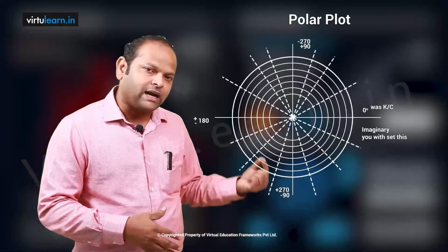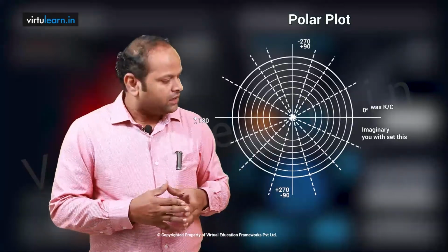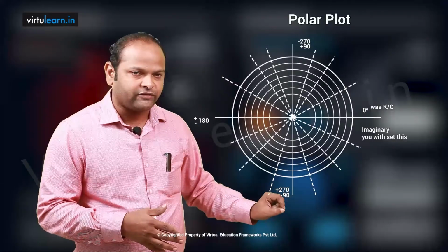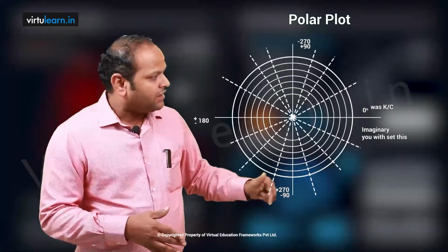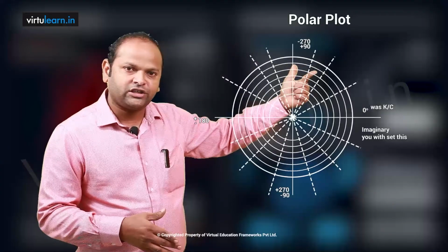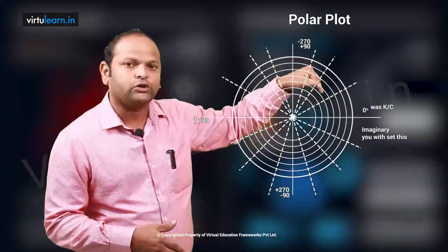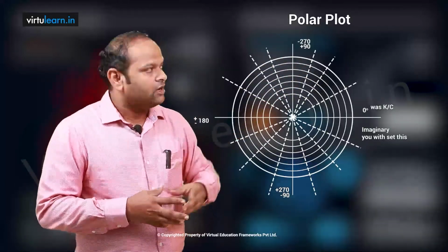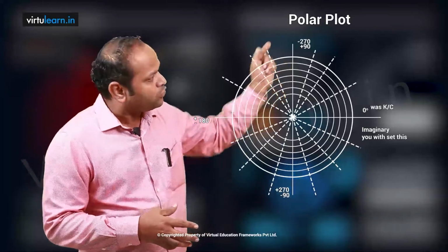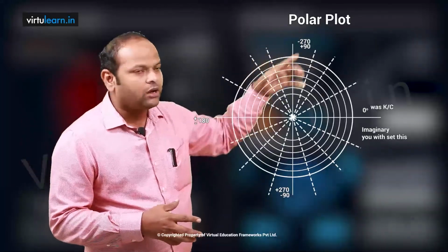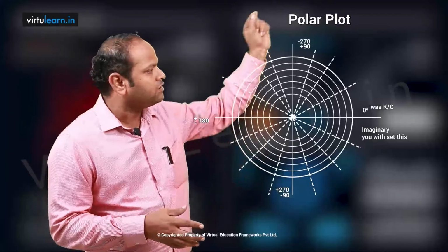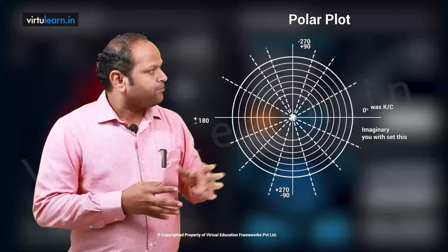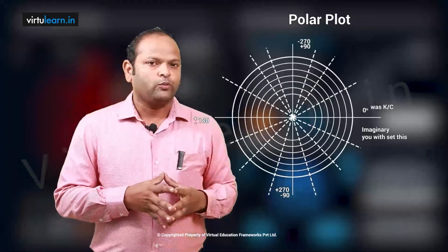When the polar plot is starting, it is coming from minus 90 degrees. Therefore, I have minus 90 degrees. Let us say here, assume omega is 0 and magnitude is infinity. Then this is the starting point, and the ending point is magnitude 0 at the origin. While it is approaching 0, at what angle it is approaching is very important, which is the ending angle, minus 270. So when it is approaching 0, it is going through minus 270. In between we have all the values. So you just draw the smooth curve, which is the polar plot of the given open loop transfer function.